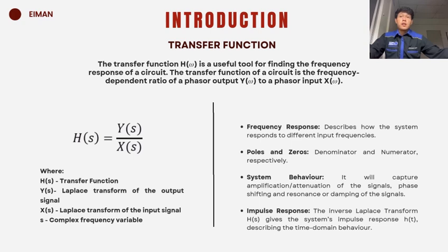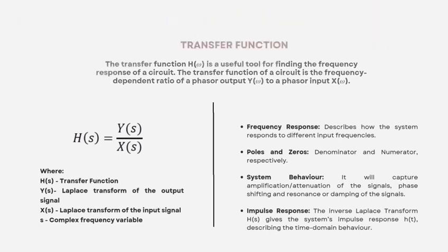And finally, impulse response. By taking the inverse Laplace of H(s), we can get the system's time domain behavior, which is useful in real-world analysis. So overall, the transfer function is a powerful method to understand and design circuit behavior, especially in control and signal systems.